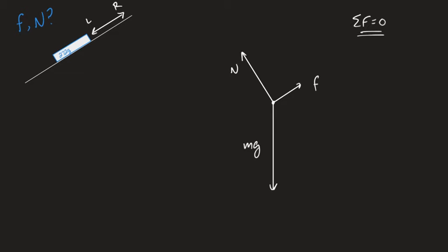You know, that has farther reaching consequences than you are probably capable of imagining right now. So let me help you imagine things. In the near future, we're going to write those things out, aren't we? So I can tell if you're really paying attention by just looking at those. If friction and normal appear in the same one, you did it wrong. You see what I'm saying, right? Friction and normal have to be perpendicular to each other, so they will never be in the same one of those. They'll always be in opposite ones of those. Always. They have to be.